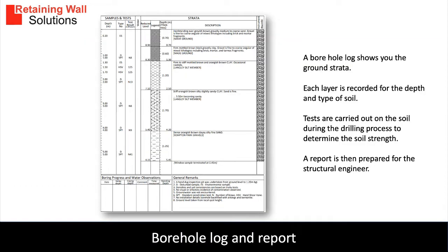This is what a borehole log looks like from a professional site investigation report. On large projects, the architect or engineer will commission a full site investigation survey. This includes looking at floodplains, soil chemical analysis and a number of boreholes carried out by a geologist technician.